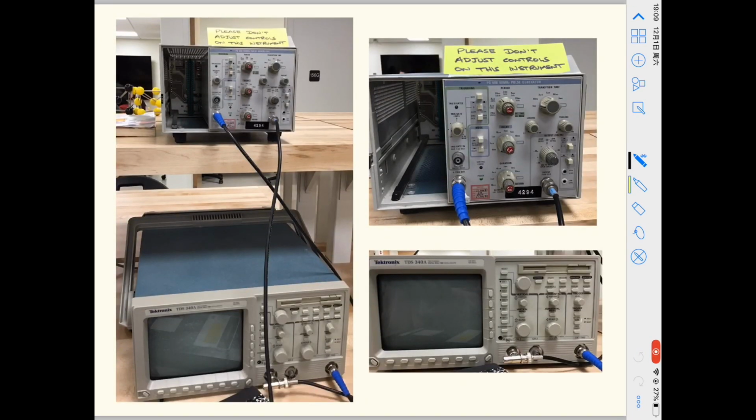So how do we investigate the concepts we've discussed in the coaxial cables lab? Here's a brief overview of how the experiment works. The pulse generator equipment on top generates a pulse, or an electromagnetic signal, with a fixed time interval. That pulse, or wave, travels through the cables in the back of the pulse generator. The resistance in the pulse generator and the cable are matched, which means that 100% of the wave generated is transmitted into the material.